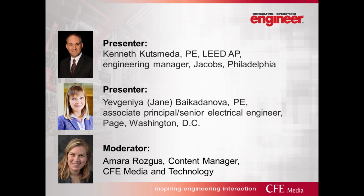Yeah, that's actually a great question and something I didn't cover. A lot of times you'll see resistance grounding in medium voltage systems, basically to limit the amount of ground fault current flowing into your equipment, specifically on generators. The generator winding and so forth just can't handle that amount of ground current, so you'll see ground resistance added to help with ground fault protection. Also, the relays seeing that amount of current can be important. So it is something we typically would use on generator systems at medium voltage.